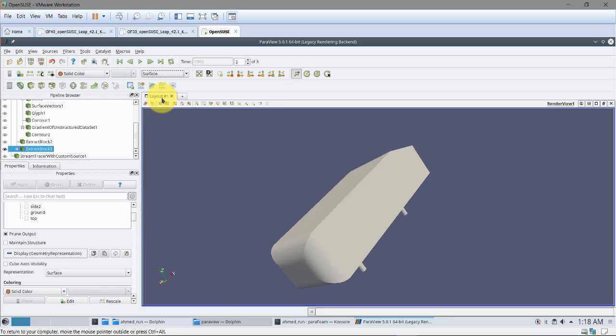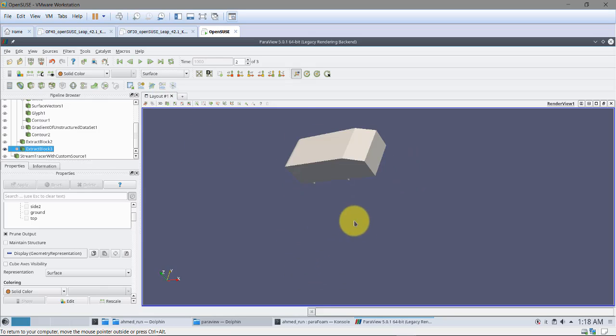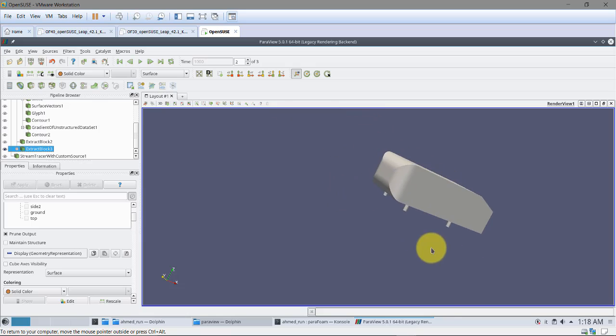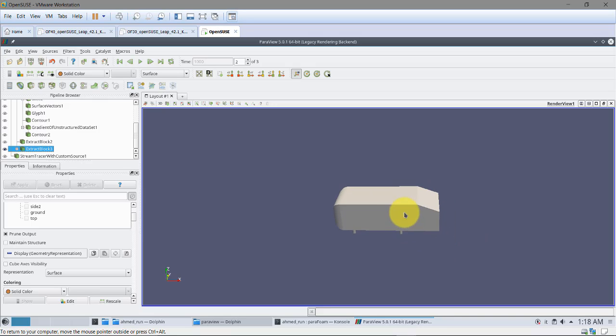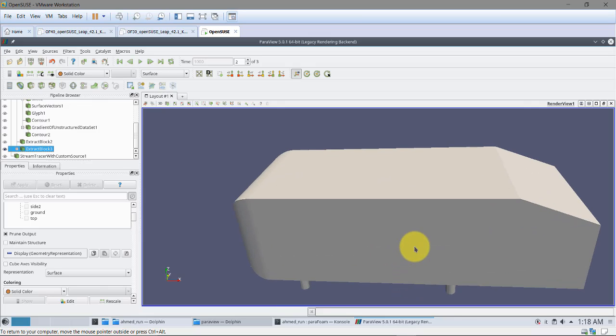So now I will show you the second option. The second option consists of, again, you need the wall shear stresses. If you don't have the wall shear stresses, you can compute them here. You can also do a kind of trick where you scale this surface, then project your velocity onto this surface and release the streamlines from that surface.